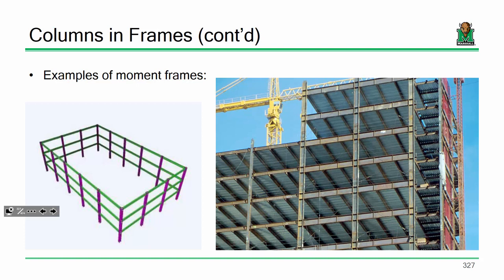Very normally shaped building, pretty rectangular, but it's pretty tall, okay? So this building is going to behave a little differently than something like Smith's. I guarantee you the lateral system for this building is different because the loads and the demands are different, okay? So that's number one. Number two, a lot of where you place moment frames and brace frames, once we've gotten that out of the way, comes from economics and, honestly, experience.